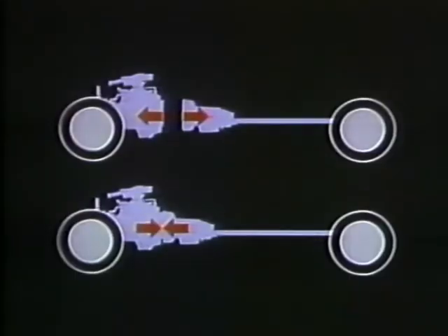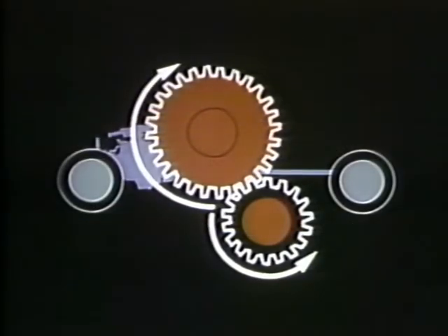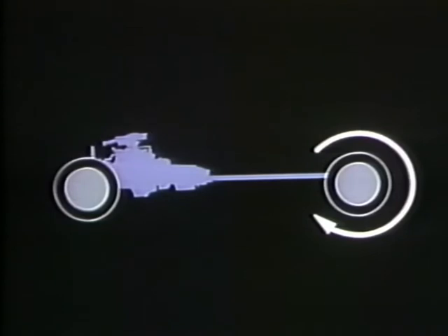To review up to this point, we have explained the three basic necessities that an automatic transmission must provide. The first being a means of connecting and disconnecting engine and driveline. The second being a means of providing gear reduction in order to move the vehicle from a dead stop up to cruising speeds. And the third, providing a means of reversing the rotation of the output shaft so that the vehicle can be moved backwards.